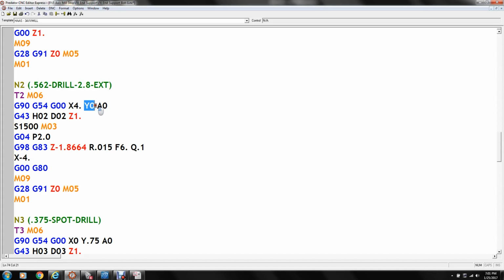You don't need a Y because the Y doesn't change. It just moves over to 4 inches. And then you wrap it up again, in this case to the 1 inch, and you cancel. A G80 is a cancellation of all of these drilling, boring, threading, tapping or whatever cycles. G80 cancels them.